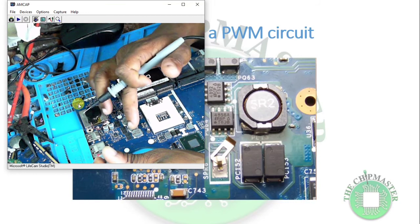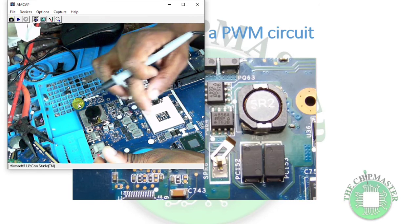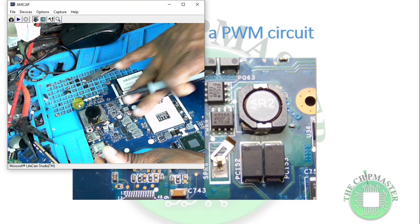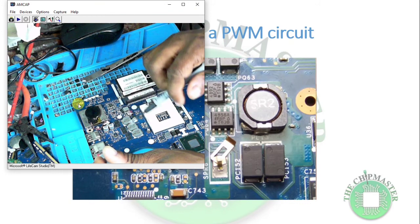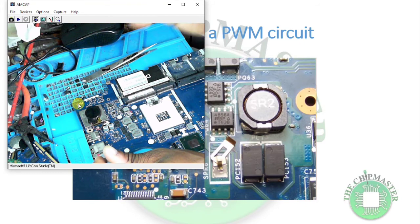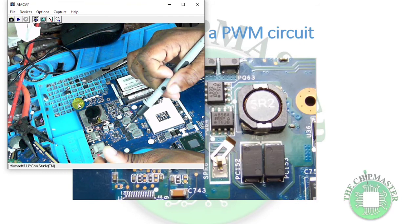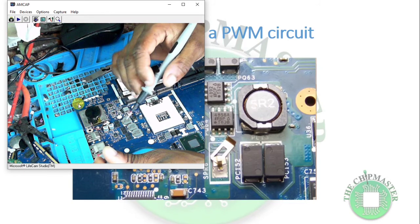So if the total amount of current the CPU power supply needs is 90 ampere, right, it should be at least 45 ampere going through one phase, because it's connected in parallel. These coils are connected in parallel, so 45, another 45, which is a total of 90 ampere, right? So normally these MOSFETs are acting as a shared current, right? That's how they designed it, right?